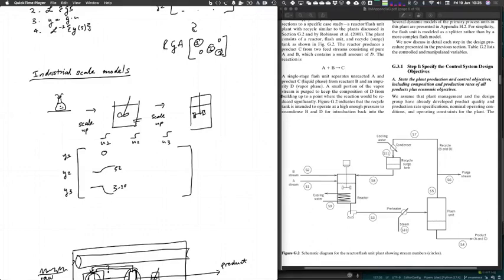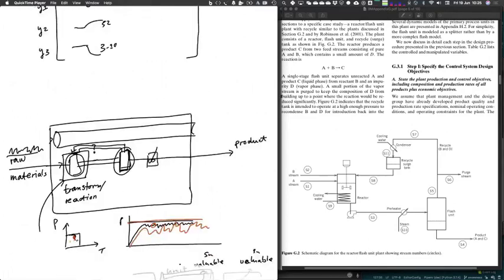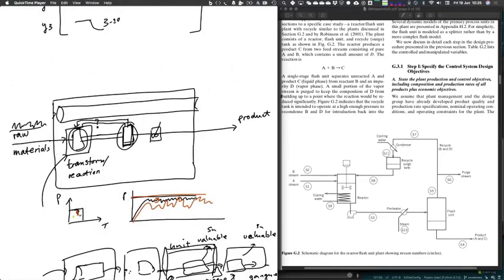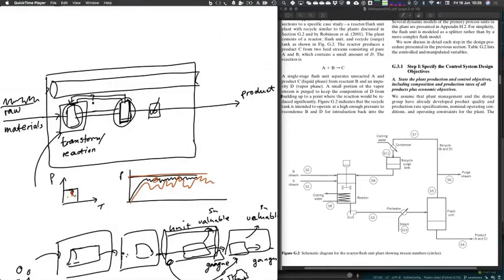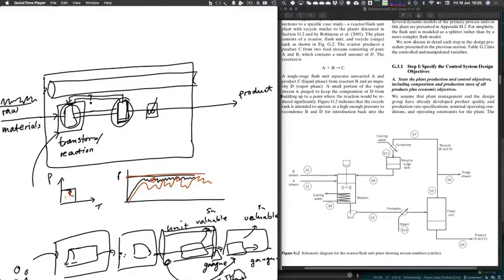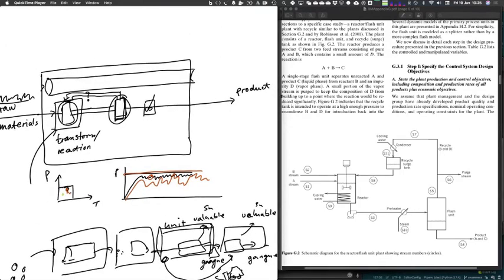So if your PID controller doesn't work at all, it's kind of useless to have a very intricate high-level control strategy, because you're always just going to be fighting against this variance, right? You're just going to be trying to figure out how to operate closer to that point, and you're not going to have the mental energy to actually figure out the correct optimal operating point.